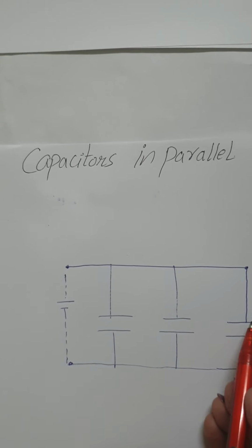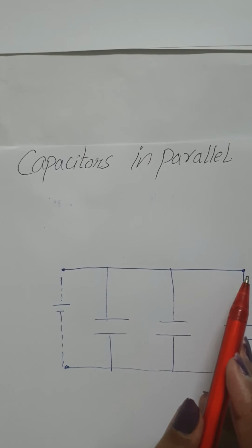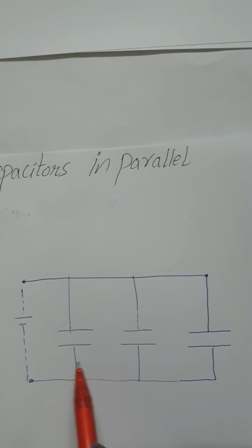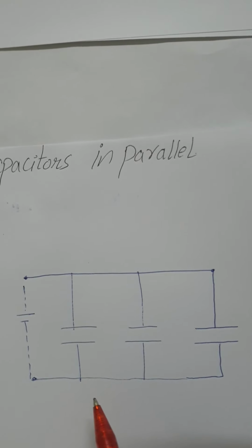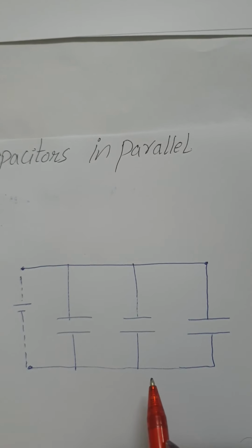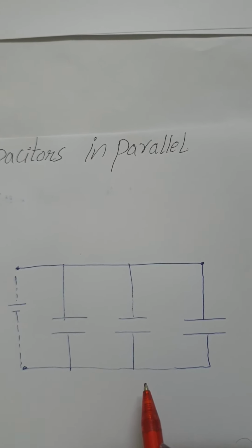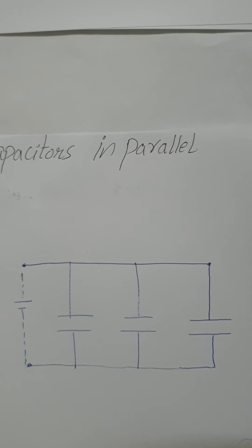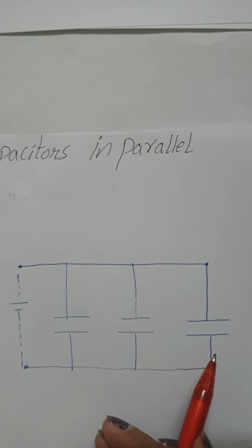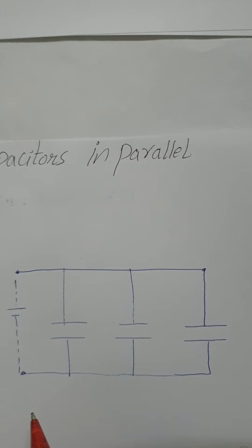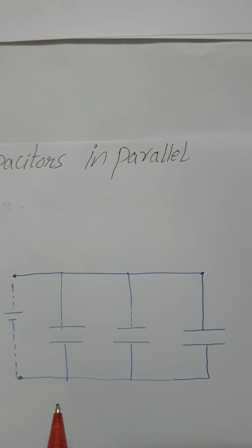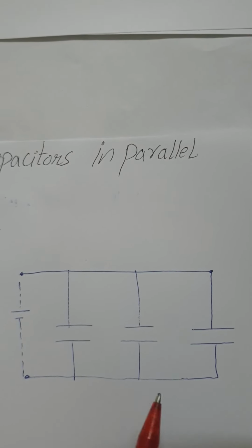and directly wired together at the other plate, and the same potential difference V is applied across the two groups of wired together plates. Thus each capacitor has the same potential difference V, which produces charge on the capacitor. So when a potential difference V is applied across several capacitors connected in parallel, that potential difference V is applied across each capacitor. The total charge Q stored is the sum of charges stored on all the capacitors.